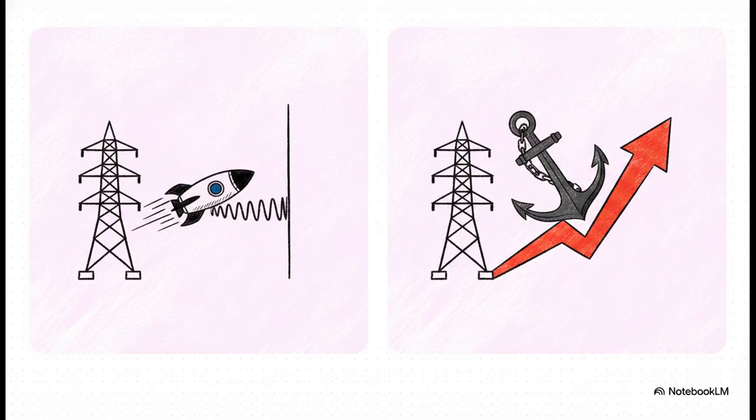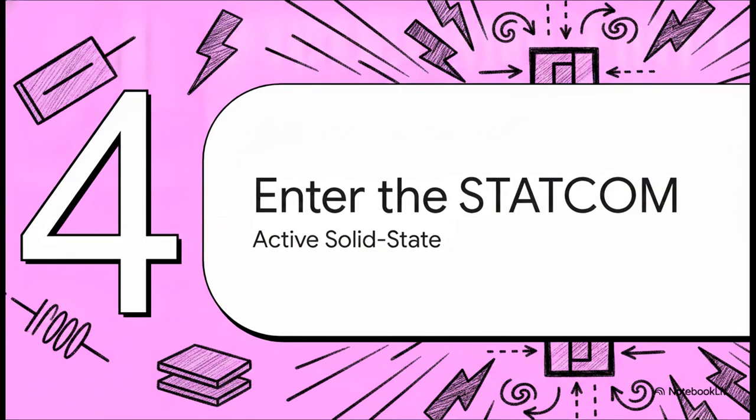Inductive shunt reactors are an absolute necessity to absorb that excess reactive power and stop that dangerous Ferranti overvoltage when the line isn't carrying much load. Passive components are great, for sure, but they're static. Let's look at Section 4. Enter the STATCOM, where we introduce active, solid-state control.